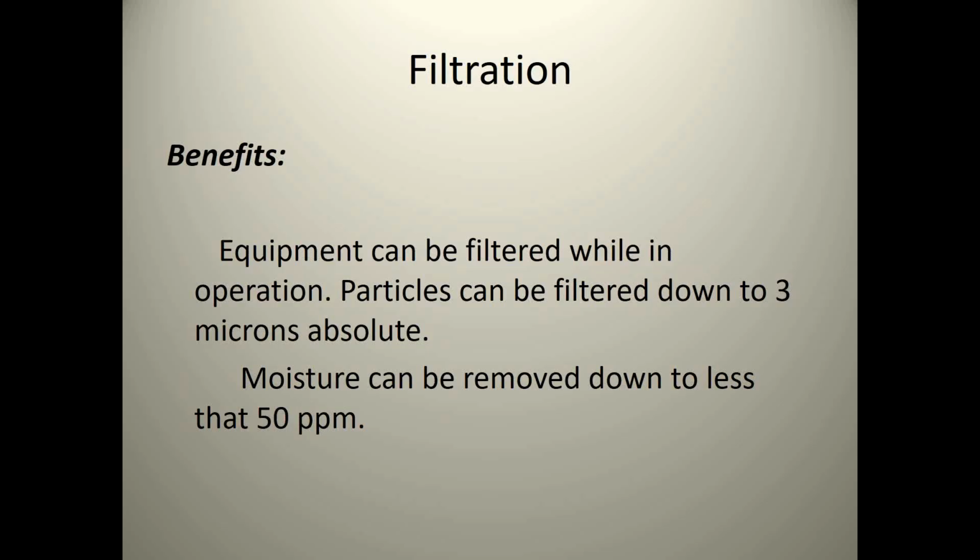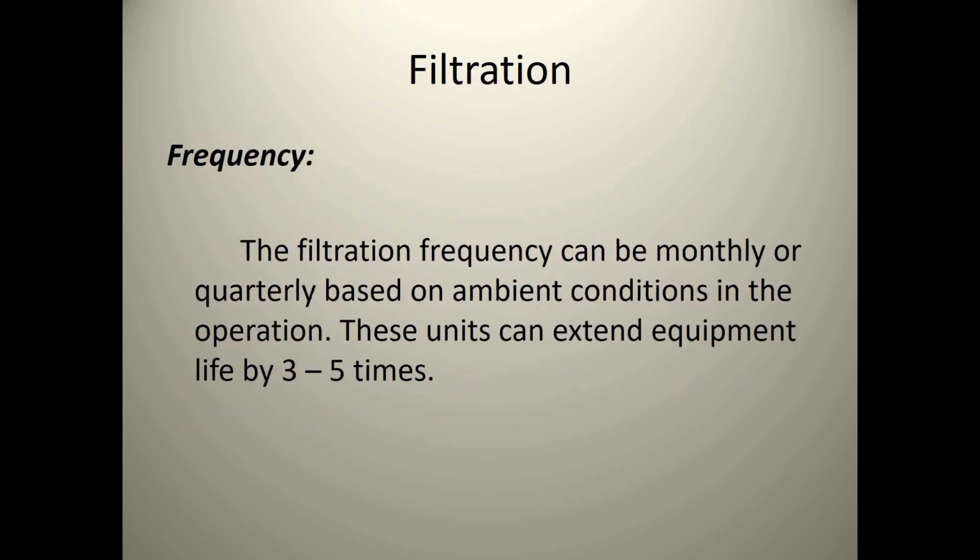But again, make sure you can filter your equipment all the way down to 3 microns. You have to be careful going below 3 microns because you can filter out some of the additives in your oil. There's also cartridges we can put on the filter carts that actually filter out moisture. They actually have desiccant inside the filter.